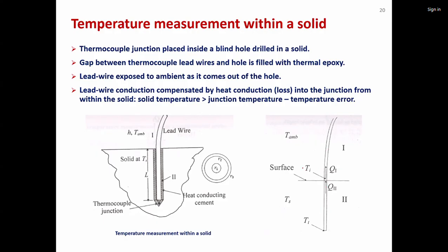This Ti is basically the temperature of the interface region. That means the point where the thermocouple is meeting the solid and the ambient, right at the surface level. Somewhere here is the temperature Ti. That is the interface temperature.